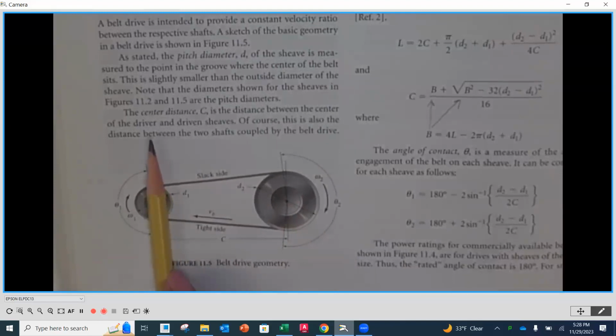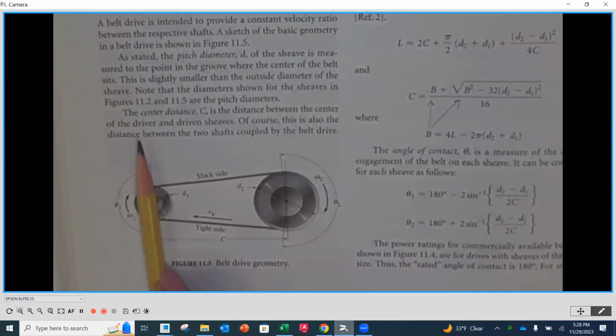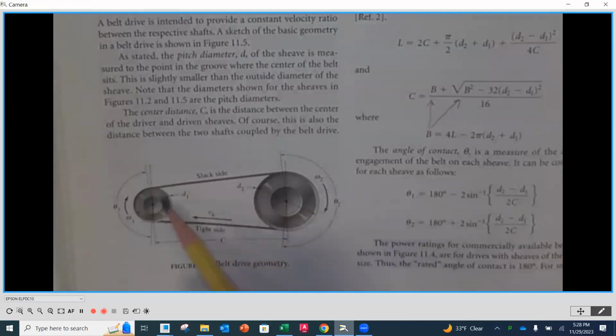Then over time, it's naturally going to stretch out. So it has to have what we call a take up on it. Many of you have probably heard about a belt take up. So you have to design that into it as well, so that over time, as it stretches, we don't want this to start sagging, or coming off again because it's not tight enough. So there is a certain amount of take up that is expected. And again, the manufacturer will be the resource for what's appropriate for the belt that you choose.